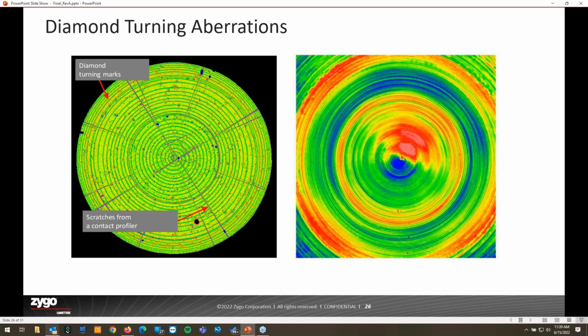That can be identified and you can calculate what that tool offset is, the misalignment of those two axes. And then that will help you to adjust and dial in exactly where your tool setup is, so that you're starting or finishing exactly at the center position of your optic. And again, that's a tool offset result that's available inside of MX.